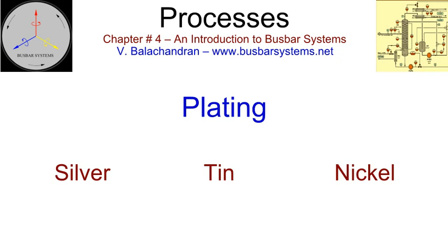A plated busbar end, tab, on which mechanical processing such as drilling and cutting have been carried out, can form several localized galvanic cells leading to corrosion. In a galvanic action, the anode gets deteriorated. However, if the surface area of anode is large compared to that of the cathode, the effect of corrosion due to galvanic cell formation is minuscule. The plating of busbar is carried out for the following reasons.